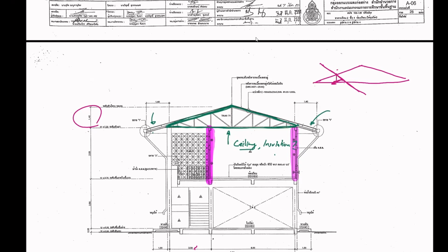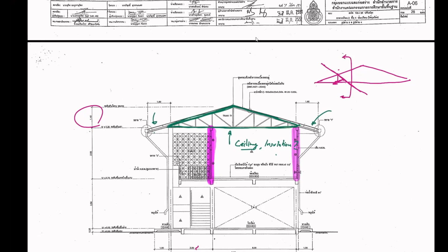If I draw it in side view, you see the top chord and the bottom chord somewhere, and then you see the purlin. You can add a member from the purlin to help brace the bottom chord if you need to. It's time to worry about this later, but this time you make sure that all the load is correct.